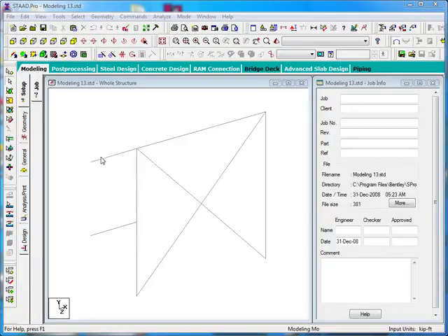Let's make the assumption that our goal in this exercise is to take the existing frame and generate 2 more copies of it spaced 15 feet apart, and in addition what we'd like to do is connect the free ends of the cantilevers and the tops of the columns. If I press the hotkey Shift K to turn on node points, we can also see that there are still some intermediate nodes along the top chord. So we'd like to connect all of those nodes with longitudinal members.